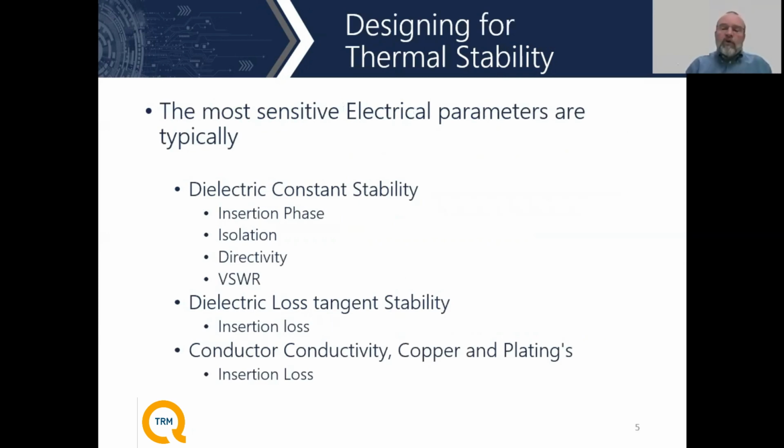Yes. So now that we talked about the criticality of measuring it, and making sure that everything in the measurement system is outside of the oven. Things that are in the oven, dielectrics for example, can change dramatically over temperature depending on the particular material you're picking. Dielectrics can change the dielectric constant of a material over temperature. Most PCB materials that are readily available today do have some variability over temperature.